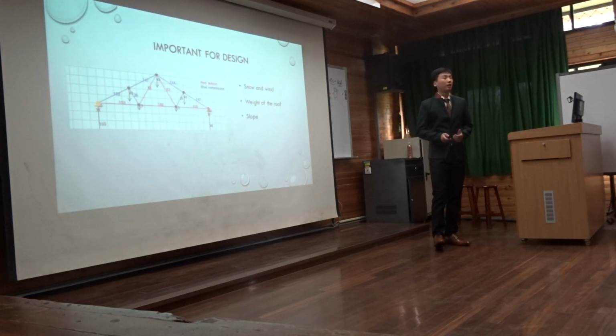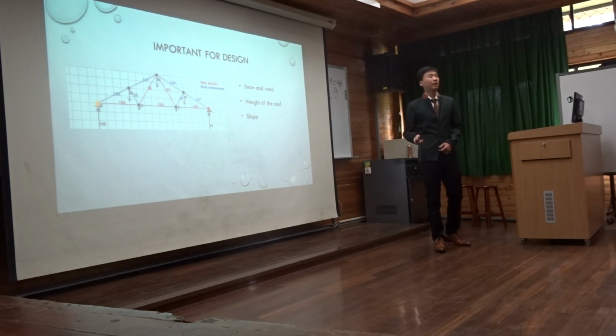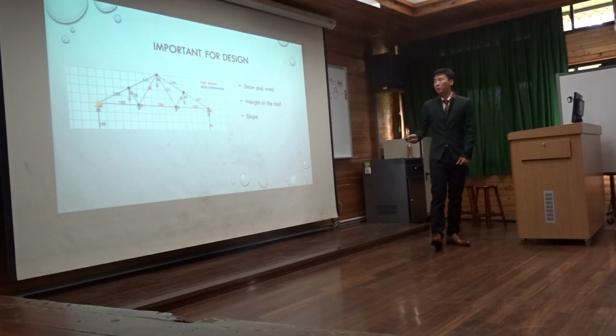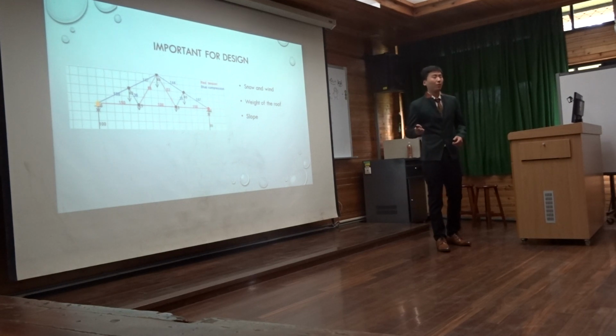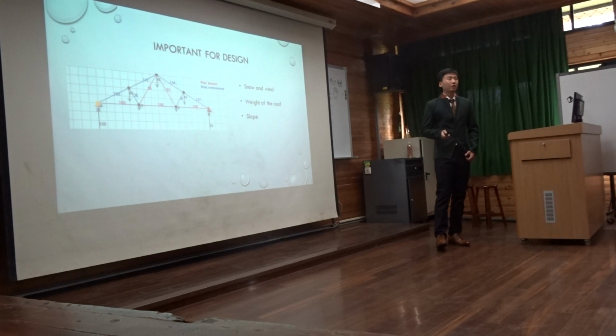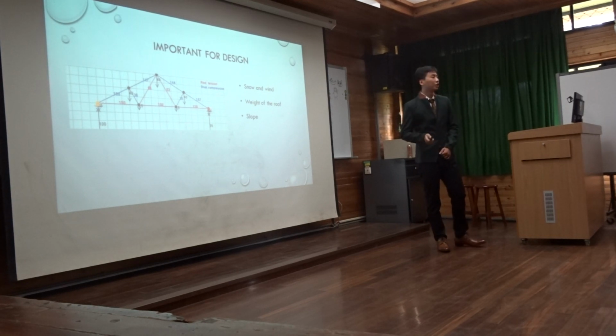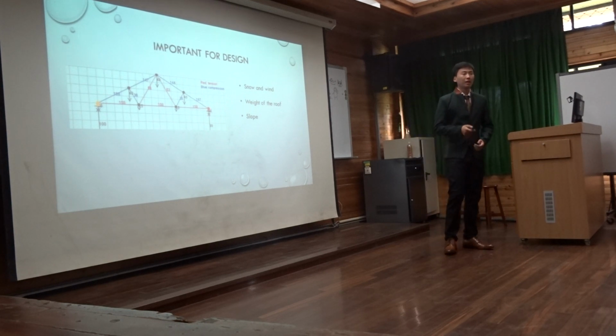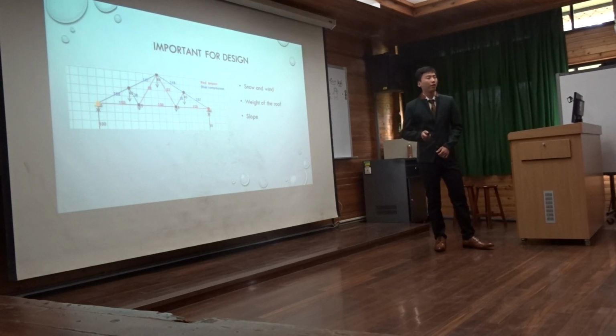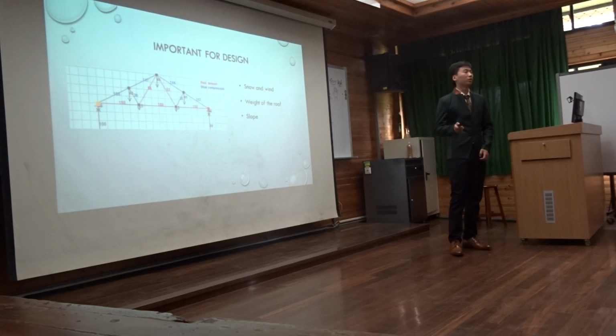When designing a new truss, we should consider not only the snow and wind loads, but the weight of the roof itself. Design also takes into account the slope of the roof. Generally, the flatter the slope, the greater the stress. Flatter slopes therefore need larger members and stronger connections in roof trusses.